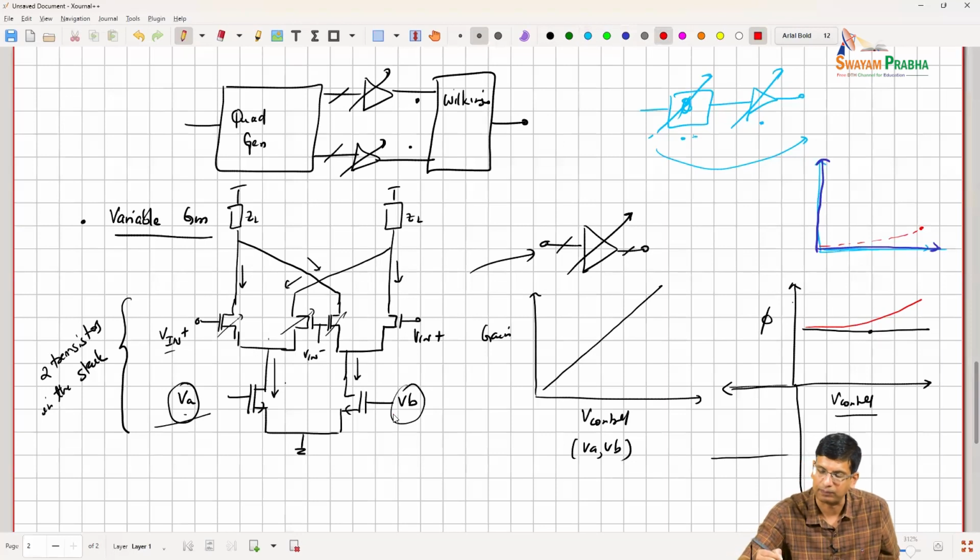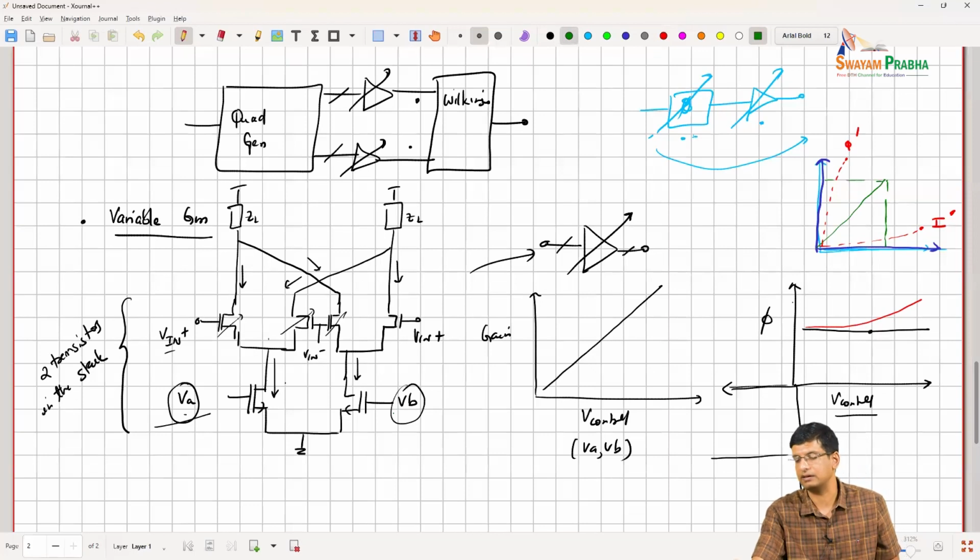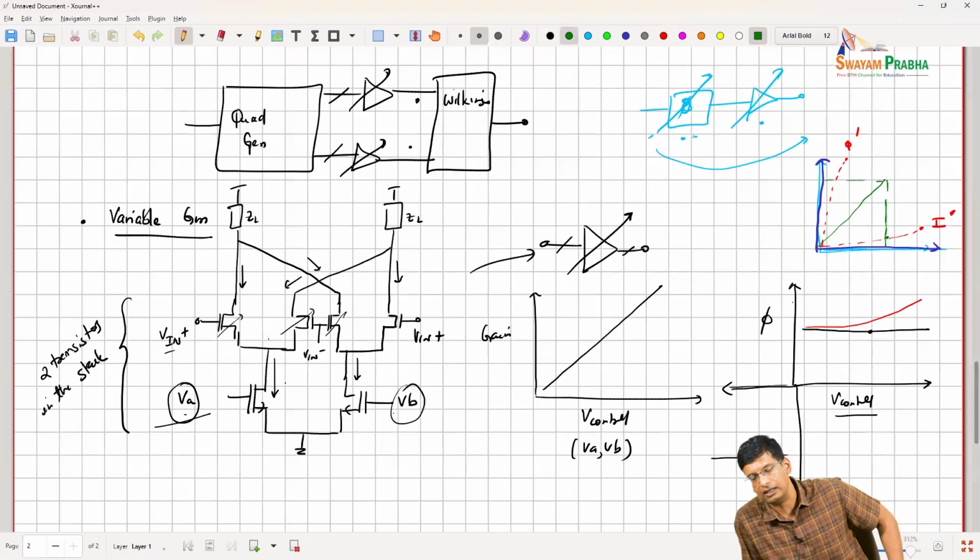So this is the new I, I'll call it I prime, and the new Q across amplitude, the phase looks like this. So if I'm trying to interpolate in order to get some particular phase, I'm actually finding that I am interpolating between these vectors, so the phase changes, as opposed to what I ideally thought.